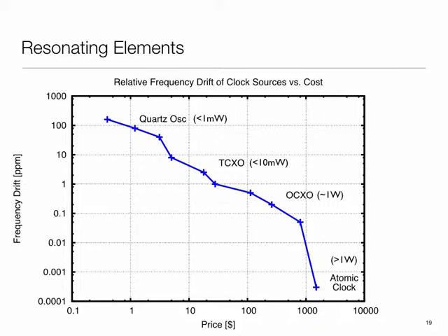Low frequency doesn't imply inaccuracy, right? Low frequency just means that I can update the time less frequently, but it does have an impact on something else. After long periods of time, it'll drift more. No, you're confusing frequency and stability. I can have a 1 second oscillator which is extremely stable. In fact, last time I had talked about the GPS giving out that 1 pulse per second. You can think of it as a very low frequency oscillator. Frequency happens to be 1 hertz, but it is extremely stable. So the two are orthogonal things.